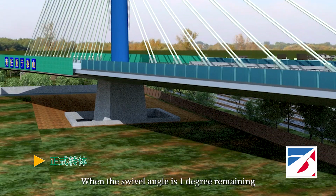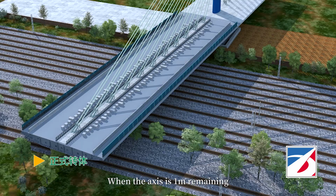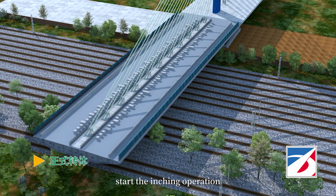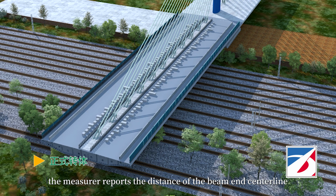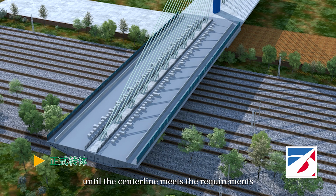When the swivel angle is 1 degree remaining, start to slow down. When the axis is 1 meter remaining, start the inching operation. After each inching movement, the measurer reports the distance of the beam and centerline. Use this method to perform multiple inching and measurements until the centerline meets the requirements.